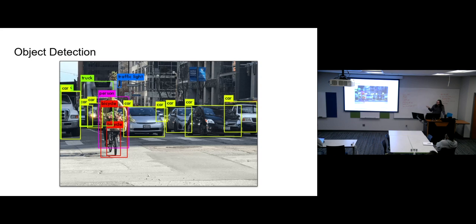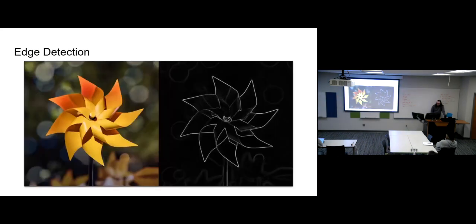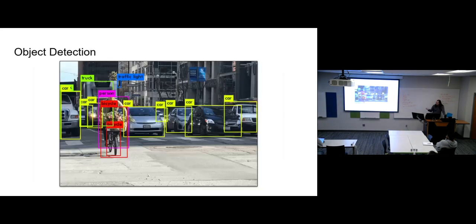When you do something like this without it, you often end up looking at edge detection and then going, if that's an artificial edge around this car, that must be a car, but it doesn't gain understanding of the car frame to frame. Something like a convolutional network and deep networks can actually follow this in video and go frame to frame. That's the same object. So that's why that's very ubiquitous now. And when you do anything with vision-based navigation, you pretty much always run into machine learning-based because of that.